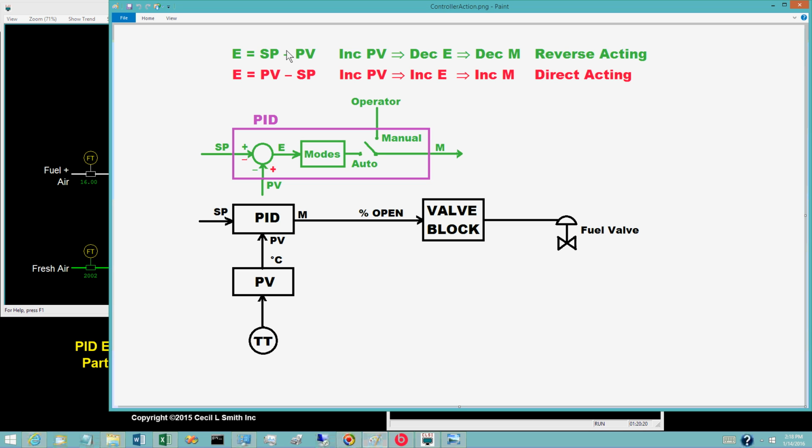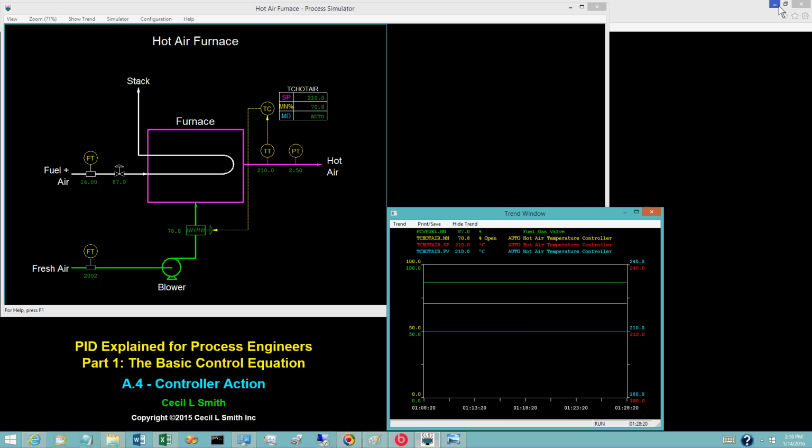How do digital controls implement direct and reverse action? Reversing the inputs of the comparator is one option, but in software, other approaches are available. Suppliers rarely provide such details, and from an application's perspective, how direct and reverse action is implemented is immaterial. It is essential that the controller action be configured correctly. Let's illustrate what happens if configured incorrectly.